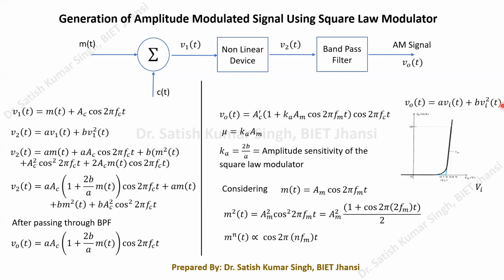These two factors are going to give you the relevant conventional AM form, which we have to look at. Basically we need a non-linear device whose input voltage is known, and whose output voltage follows this mathematical expression: A Vi(t) plus B Vi squared(t). Any general purpose diode can serve this purpose.